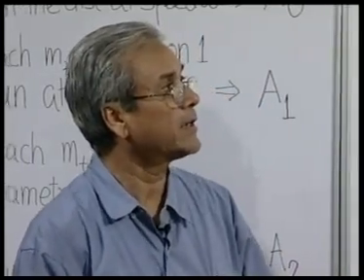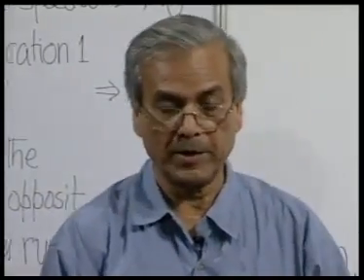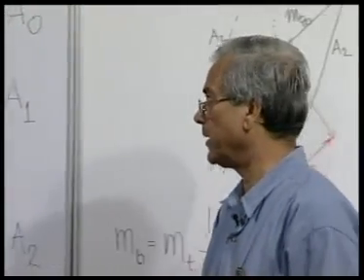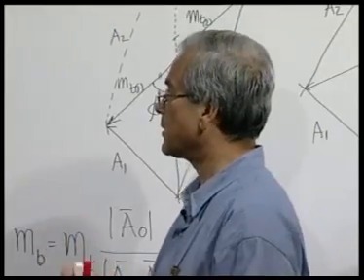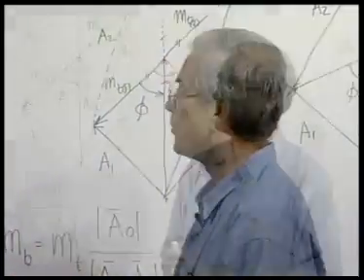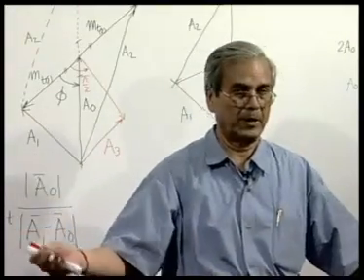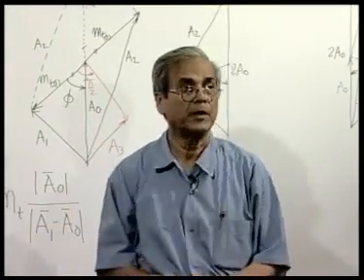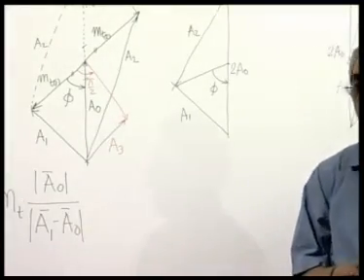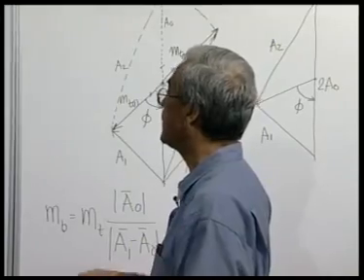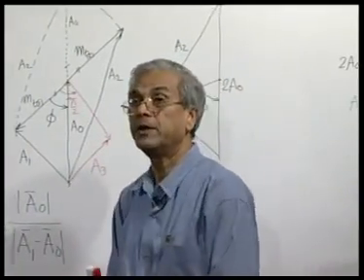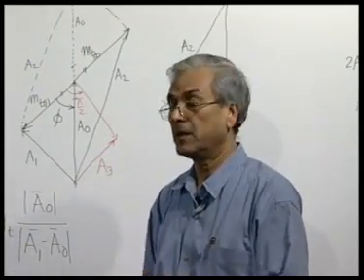Now, I think in the next session we will extend this technique of disc like objects for finding out the balancing mass required, by some experiments in the field, in its own position for rotors. That is a very major problem. A large number of systems are extremely critical from this point of view of balancing, like alternators, turbines and so on, where they are very heavy and they have to be balanced in their original position.